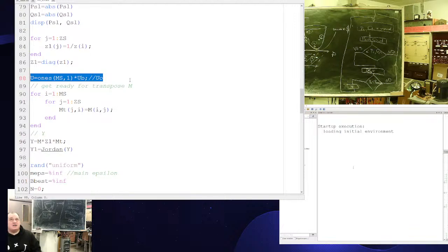I'm limited by a net code. I can go up 10% and down 5, something like this. It should be somewhere in the national code, but okay, I choose 150. Actually, it's a separate task to choose a base node voltage or setup for the voltage control system of my network. It's a separate task.